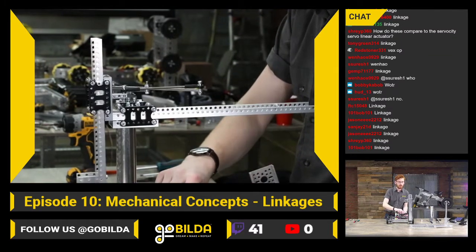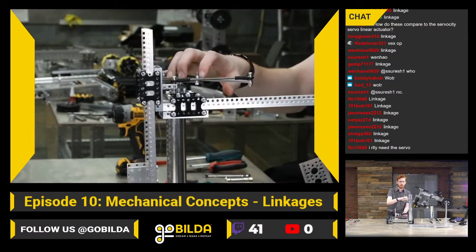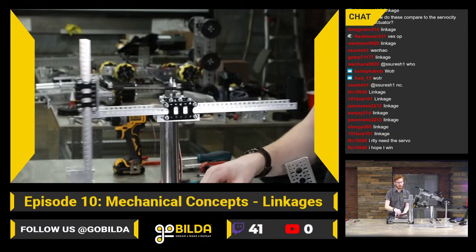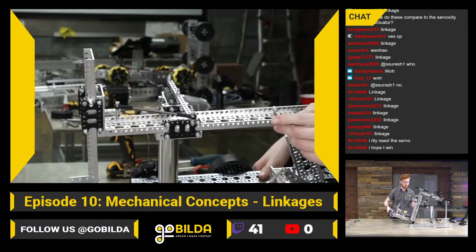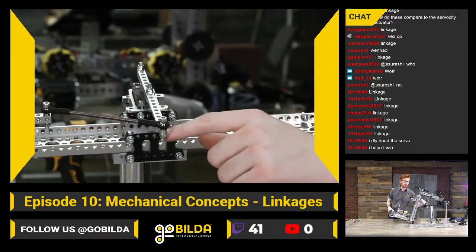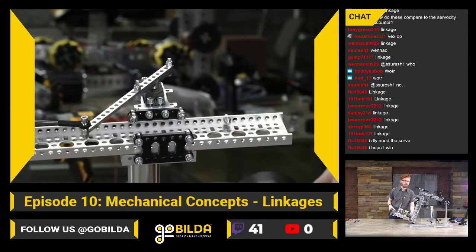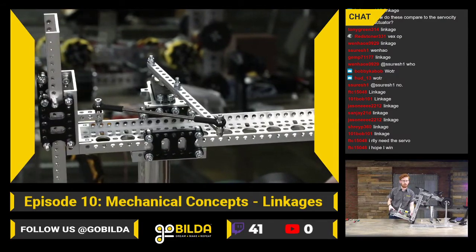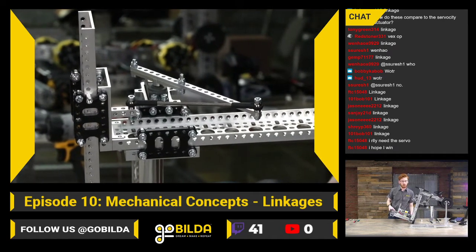So it's pretty fast, and a lot of that speed is because of the really long lever arm that you get on this linkage system. Exactly how it's constructed is there is a beam bolted to a servo arm, and that beam is running the whole length of its first bar. That gives you a lot of speed because the length of that first arm really does have a huge effect on the effective ratio of your linkage.